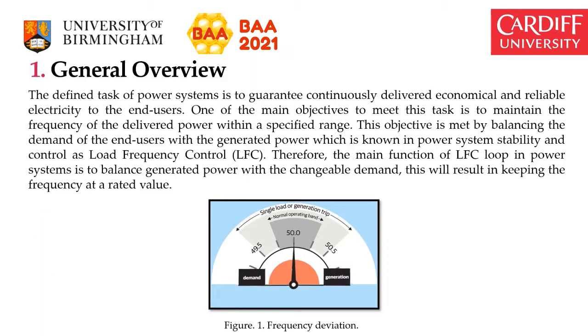The stability of power systems has always been an important topic. Load frequency control or automatic generation control is a key service to maintain the stability of power systems. The basic role of this service is to control the frequency and keep it at its nominal value, and also to maintain the interchanged power between control areas at pre-specified values. Therefore, the objectives of load frequency control are to make zero steady-state error in frequency variation and tie-line power deviation, and also to reduce the undershoot, overshoot, and settling time.